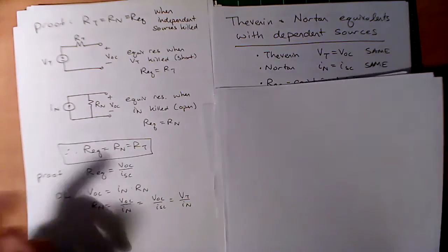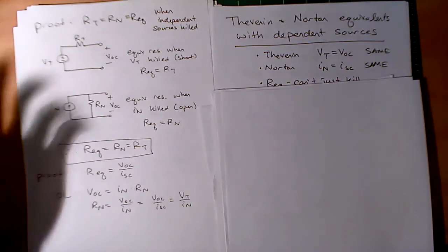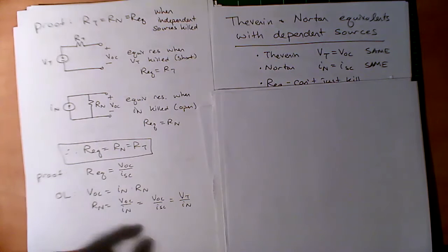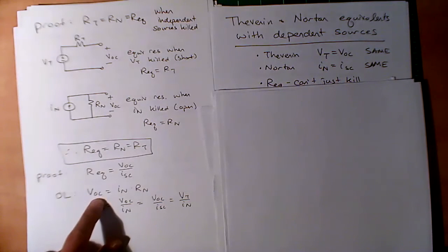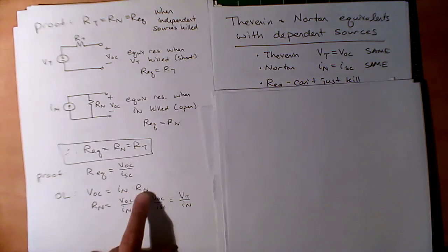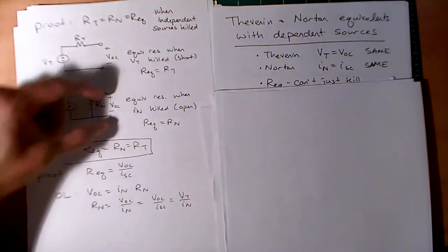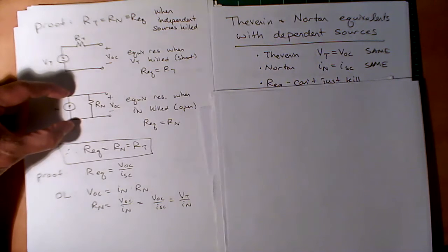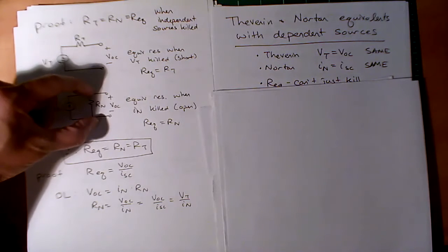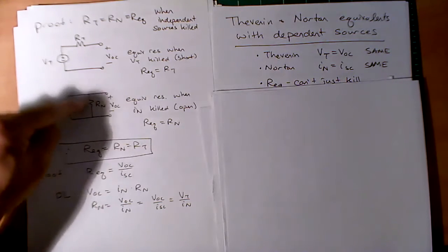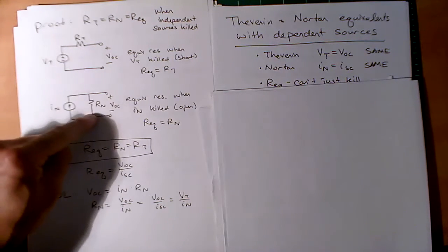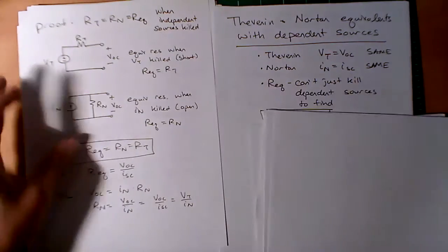And this just shows that this behaves like an Ohm's law, right? And so that's where you get your Ohm's law relationship between VOC, Norton current, and RN, right? Just here, this VOC is the same as this voltage by KVL, and that's the same as this voltage here. All this current's running here. Ohm's law solidifies and brings everything together, and that's shown here, okay?